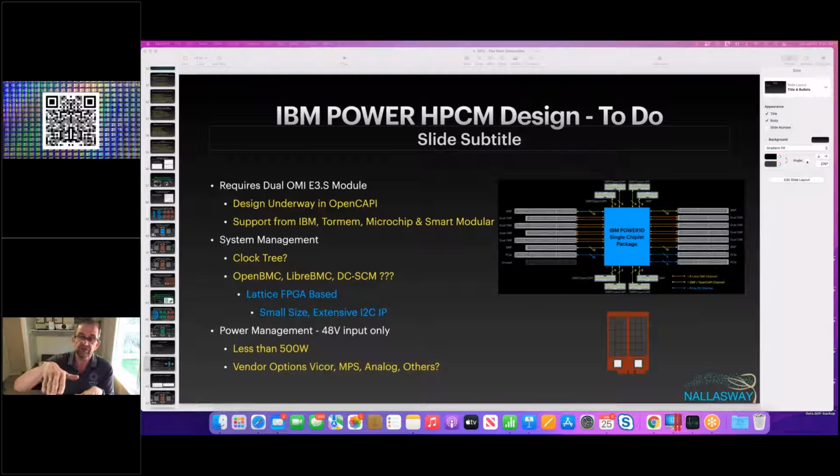So the processors sit in a standard server and they cable down to this accelerator. Now, by us building this Power 10 module, we don't need to go via the host interface board, because the host is now one of the modules in the chassis. But the key thing is, these modules all talk to the same host interface board, which is a bunch of PCI switches.